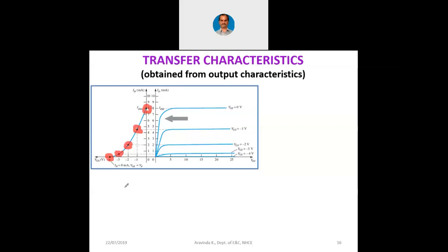If at all you plot this curve for BJT, it will be linear because of beta. But we did not plot this curve in BJT because it was not required. Why? Because we knew beta. When we knew beta, we could use beta for our calculations. But in JFET, there is no beta. And how do we bias our circuits later on? How do we set a Q point? For that, we require something called transconductance. As beta is not there in JFET, we only have to find out transconductance, for which the symbol given is GM. That I'll discuss later on in the future classes.